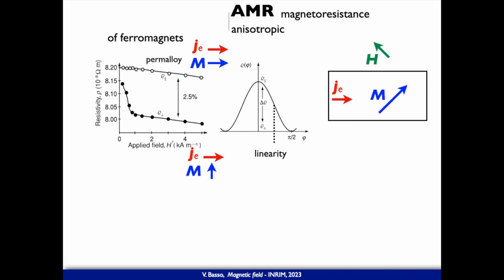So if we are able to rotate the magnetic field by 90 degrees, we pass from high resistivity to low resistivity in, let's say, a cosine type of way. Imagine you want to build a magnetometer. You want to use a magnetic field to change a little bit the angle of the magnetization with respect to the current. So you would like to put the magnetization at 45 degrees and then use a field at 90 degrees with the magnetization to make just a small rotation. The point,